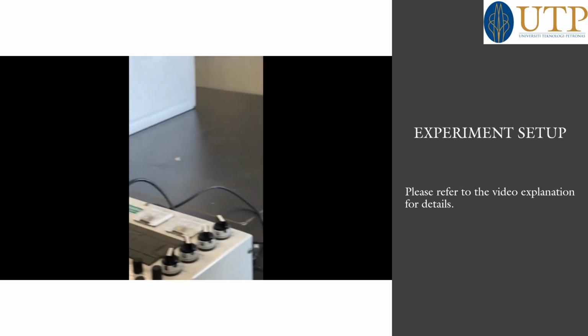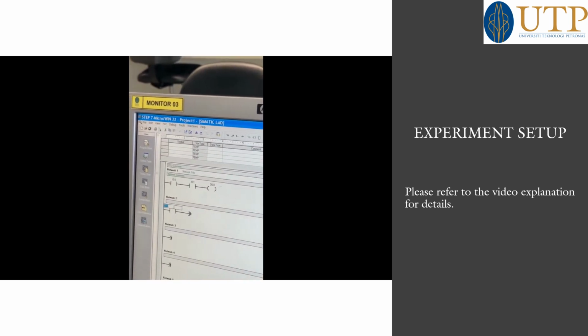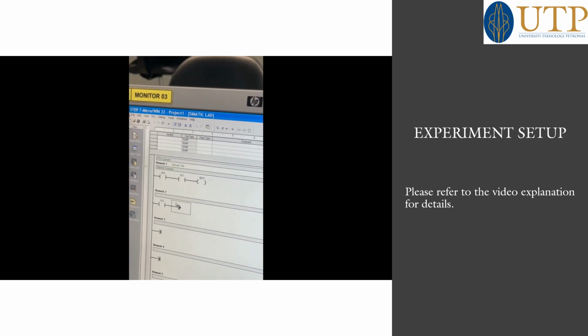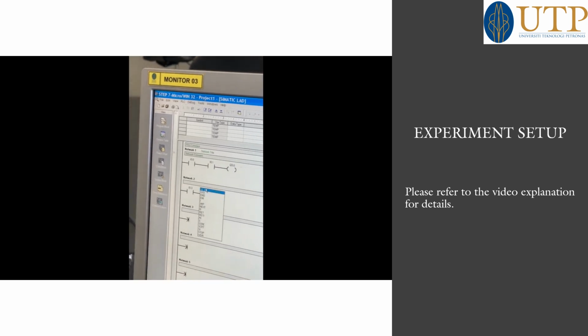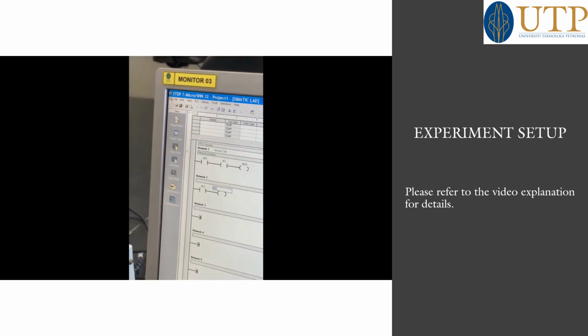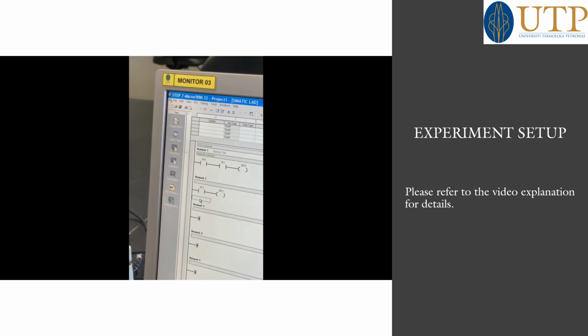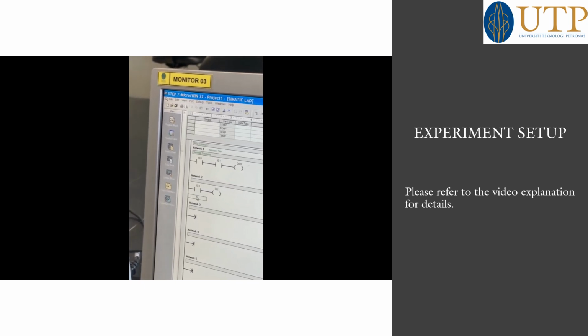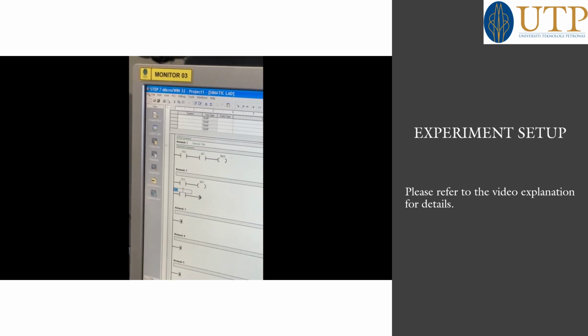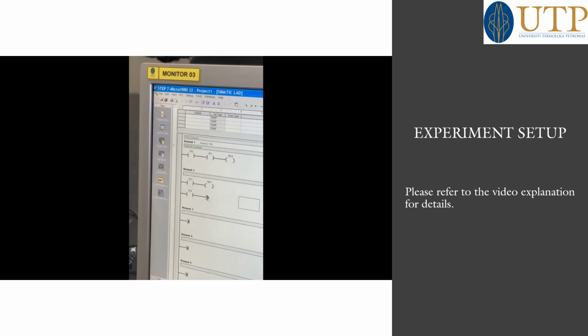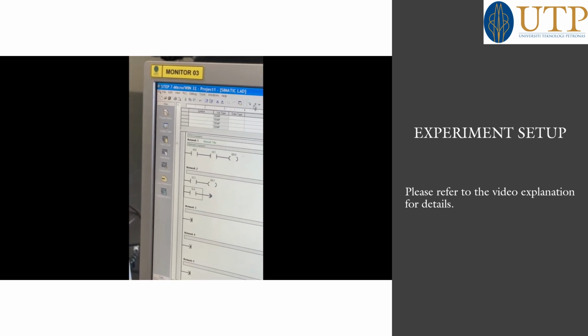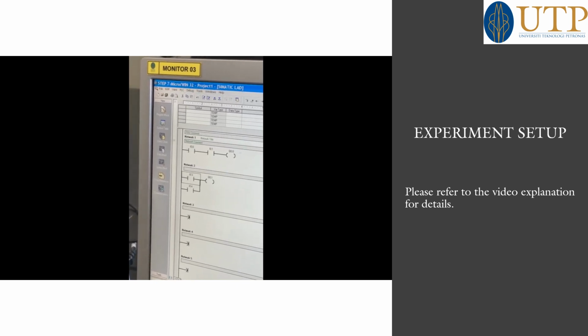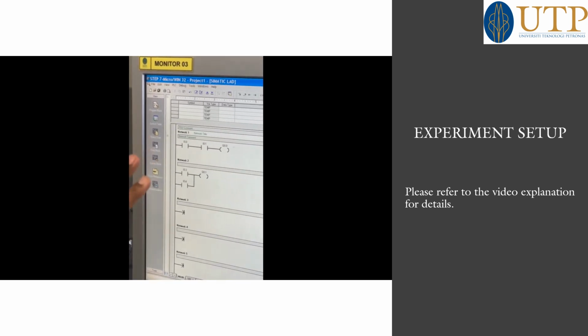And if you check the second one, he has given 2 inputs, again I0.3, this is output Q0.1, and you have to click at the bottom of this I0.3 and again open the open circuit, give I0.4, click on the I0.4 and click on the up arrow, so it will be connected parallelly. So now you have finished writing the code.